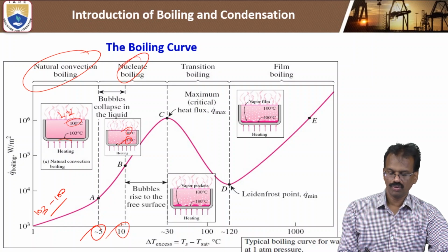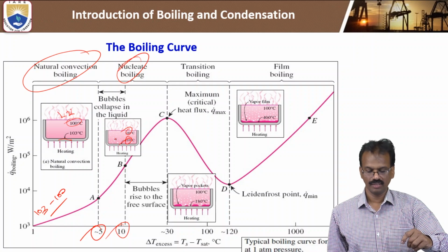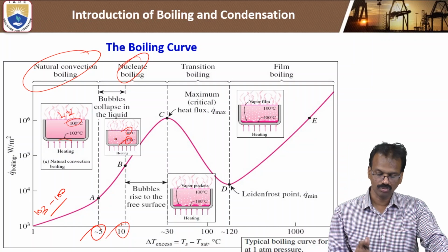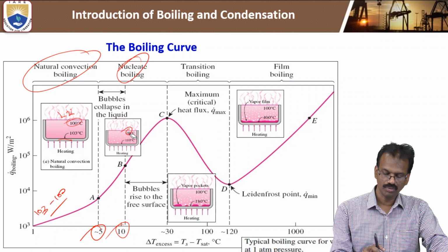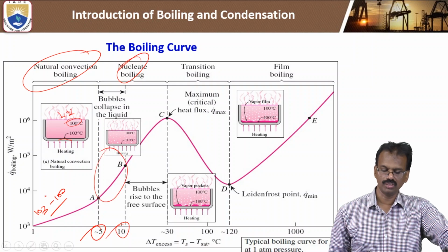Here bubbles are formed, and these less dense bubbles move in the upward direction. When they are moving, because of the lower temperature, these bubbles recondense and convert back into liquid. So these bubbles are not stable. These bubbles condense to liquid. Here in this process we will see this one.